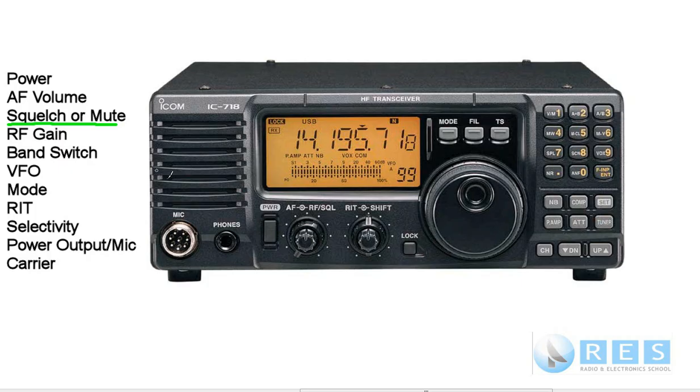signal is received. And the squelch control on this radio is this outer ring here. We've got an inner ring, a middle ring, and an outer ring. And this lever here is the squelch control. So you'd rotate that in a clockwise direction until you heard no sound coming out of the receiver. So that eliminates the receiver noise when there's no signal present. Very easy control to use.